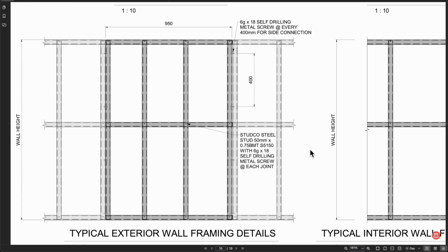So this is a lining wall that gives me a space to put more insulation in to meet the codes for thermal shell 7-star rating. So it's probably not going to make sense why the engineer has given us these little skinny studs and then big fat ones inside, because it's usually the other way around. But for this design, it's part of meeting the code.